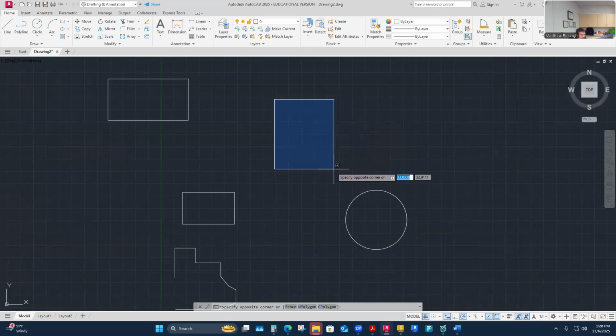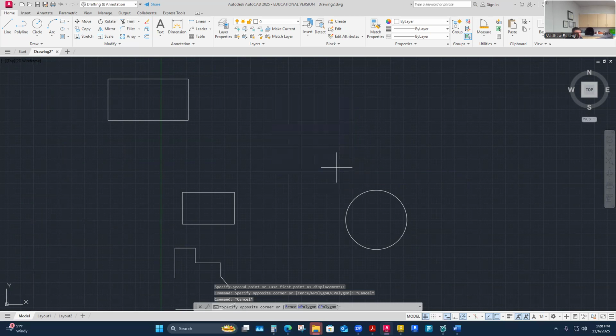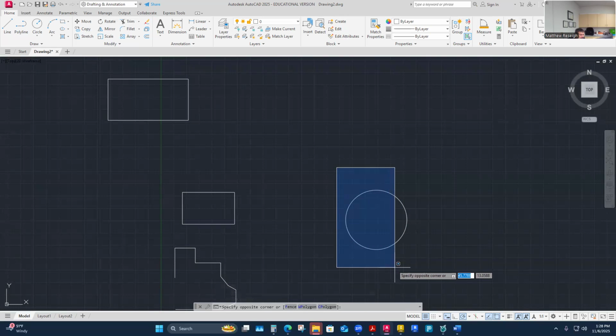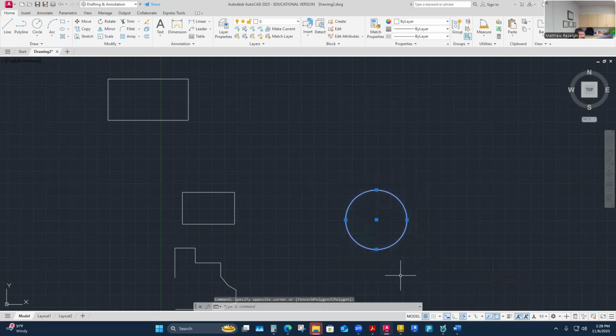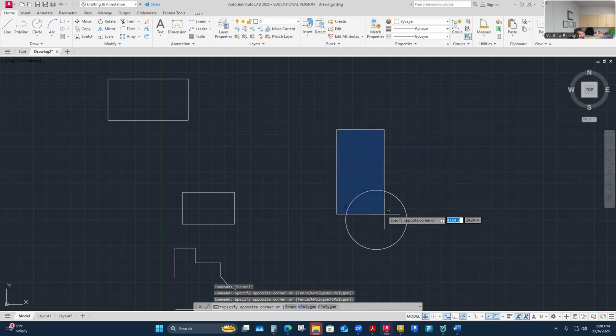If I drag and pull this across geometry, it's a way to select it. When you have a blue window like this, it has to capture all of the geometry to select it. The blue window grab does not work if I only cover partial geometry. This is just me clicking once and then pulling away, like a rectangular box, in order to select.